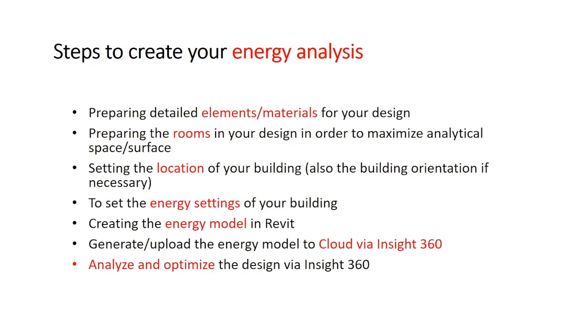And then after that, once you have set the energy setting, you will need to create the energy model. And once the energy model has been generated, you can upload the energy model to cloud. As you know, Insight 360 is basically a cloud service, so you can just send it out to the cloud.